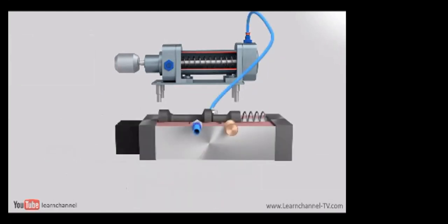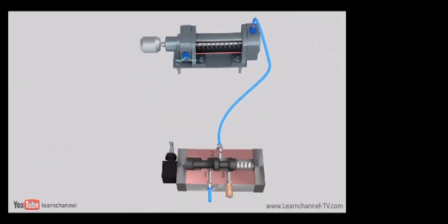As the single-acting cylinder has only one inlet port for the compressed air, you would use a 3/2 directional spool valve. In our example here, we use a spring-loaded directional valve. Due to the built-in spring, the piston returns to its base position in case of a power loss. Besides this, the air consumption is about half of a double-acting cylinder of the same size.